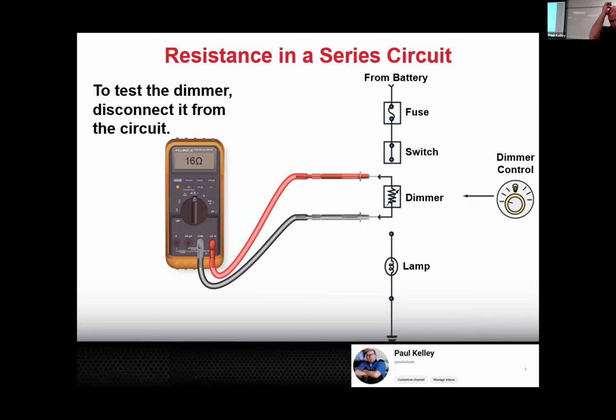The thing is, when you're measuring resistance, we're using our little 9-volt battery in the meter. Your 9-volt battery is sending electrons out. If you're still connected to the 12-volt battery, you're going to get a negative ohms reading. And if you see a negative ohms reading, not only does it have no resistance, it's almost like extra electrons are making it. Yeah, that's because it's still connected to the power source. So that's your chance to correct. You didn't hurt the meter, you just got a bad measurement, misdiagnosed the car. So not a real big deal.